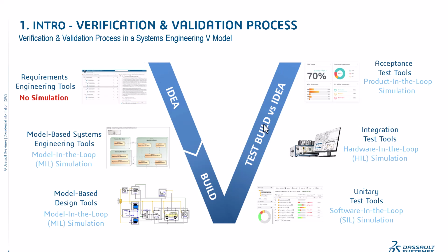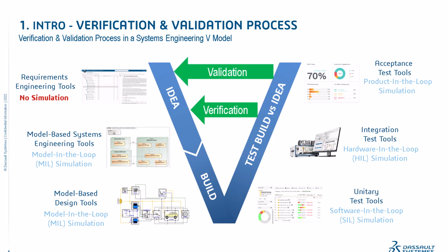So what we achieve here is actually speed up. We achieve faster verification, faster validation due to faster changes coming to the prototype of the system. So you can expect that the system will work just based on the design, but actually if you put hardware in the loop, a prototype of the hardware, not all the possibilities, but just one of the prototypes, you immediately test many different scenarios.